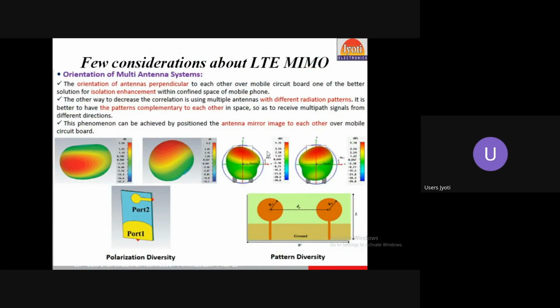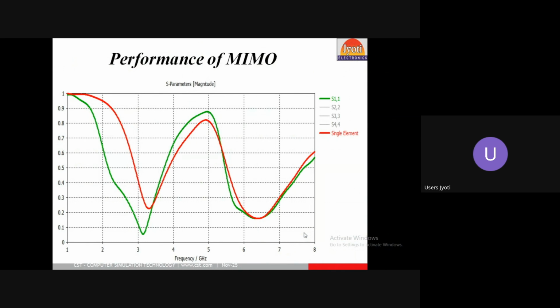Also you can see the LTE MIMO antenna. Some assumptions are there for this type of antenna, and particular geometries. Here we use a circular patch and half of the ground. You can see the ground plate is cut at the port, an introduction in the ground plane. Different methods are used in MIMO antennas after designing, especially for improving results and the directivity of the antennas.